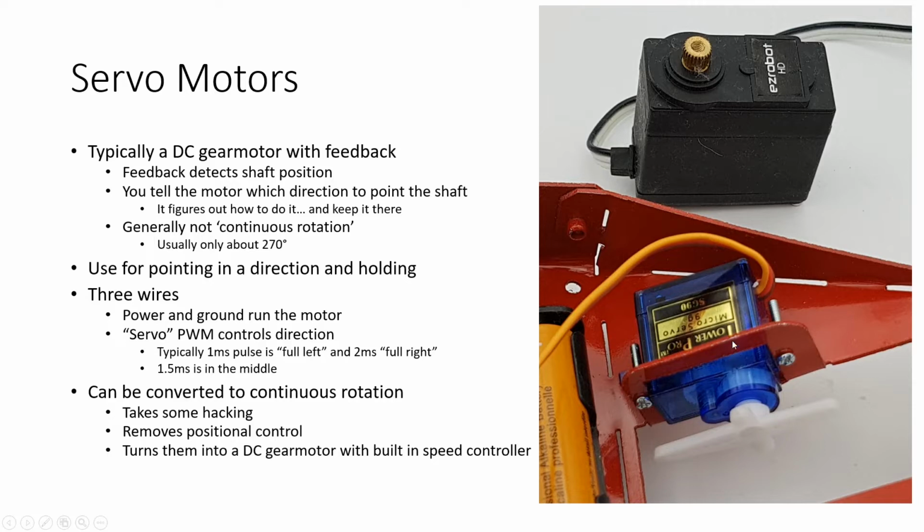What you don't see in this part of the motor is that there is a potentiometer, very similar to the potentiometer that you use with your Arduino. And as you know, when you spin that potentiometer, you get a variable voltage signal coming back from it. Well, the potentiometer in here actually feeds into a little control board at the base of the servo. There'd be one tucked away right in here, and it would read the position that the servo is in, and then figure out what position you're telling it to go to.